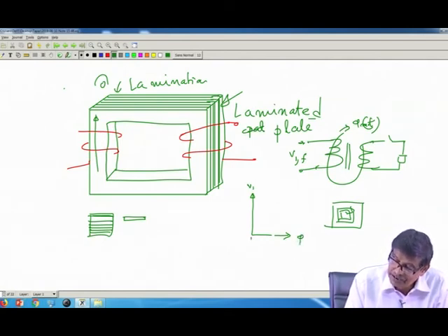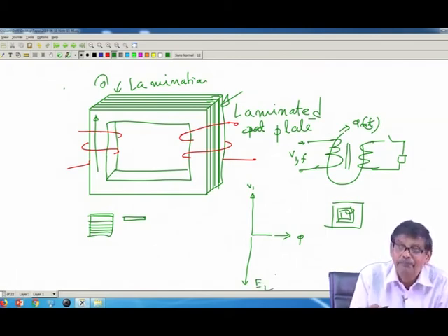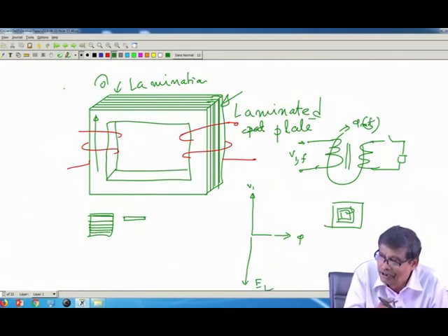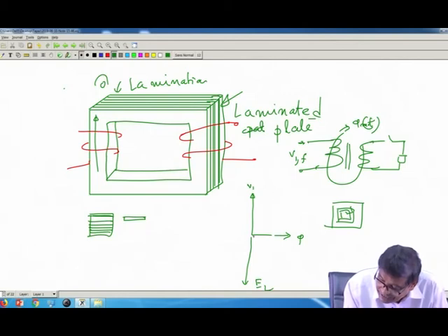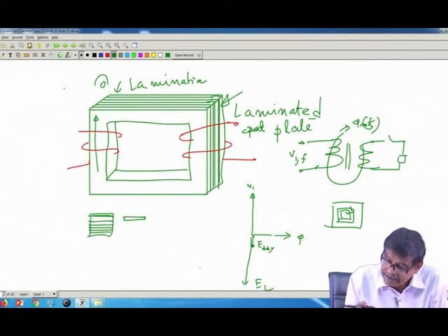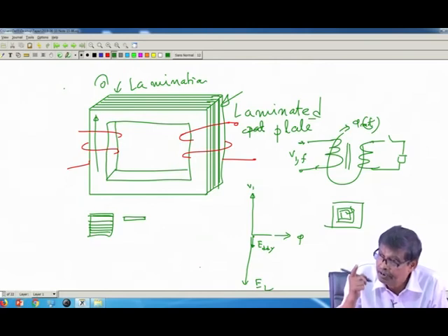There is induced voltage in the secondary too. But what I am telling is, there are some invisible secondaries already present in the core, and they have induced voltage also in the same direction. Why not? And I assumed that the power factor of that eddy current path is unity, neglecting leakage inductance.